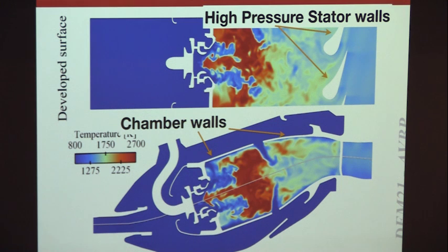But the thing you don't really necessarily see is that when you do that, the flame will deliver high heat flux to you, so that means the flame will be cooled down also. And you remember that this was shown by Paul, any level of heat loss on a flame is not something that the flame likes. And if you cool it a little bit, then the flame dies. And this is what will happen at a wall. The wall will suffer because it will be heated by the flame, but the flame will die at the wall. And so it's the combination between the two that we need to study.